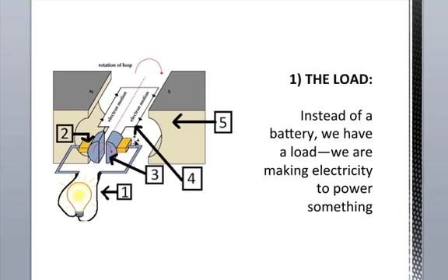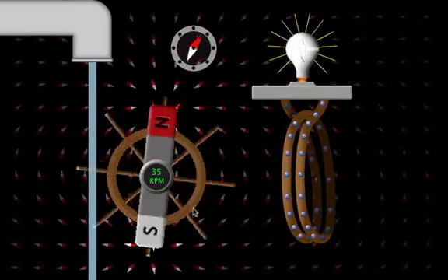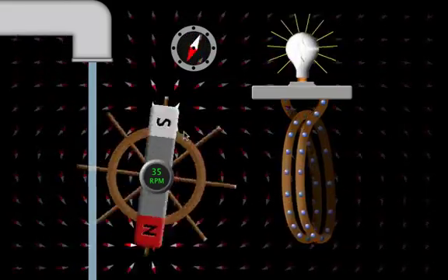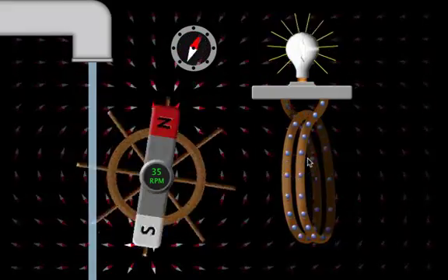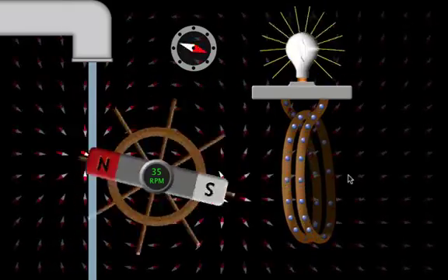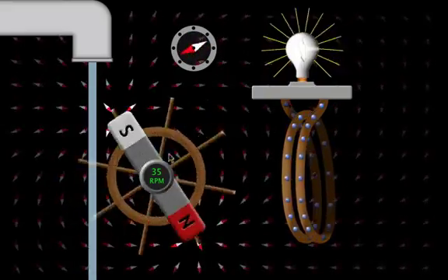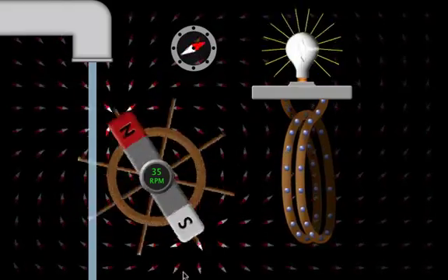As this armature turns, these permanent field magnets are going to cause the flow of electrons through this coil of wire, just like in here. As this thing moves, it's causing a flow of electrons. So in this case, we've got a bar magnet moving relative to the coil of wire, but we could reverse that. With our motor, we're actually moving our armature, our coil of wire, relative to a stationary field magnet. So the two processes are completely reversible.